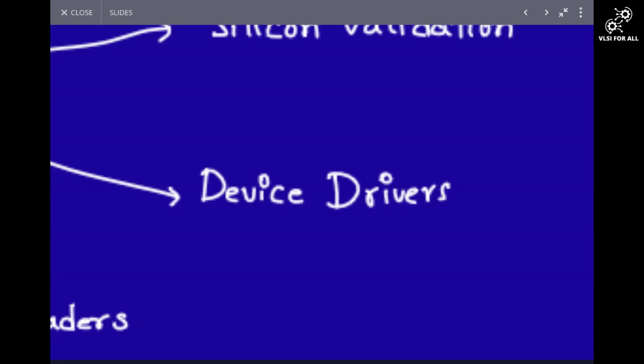So generally in embedded systems, in simple microcontrollers, we ourselves write the driver for that sensor. Let's say an I2C sensor, LM75, designed by Texas Instruments. Now, as embedded software people, what we do is we go through the data sheet of that sensor. We understand how to do calibration for that sensor, how to calibrate it before you can use it.